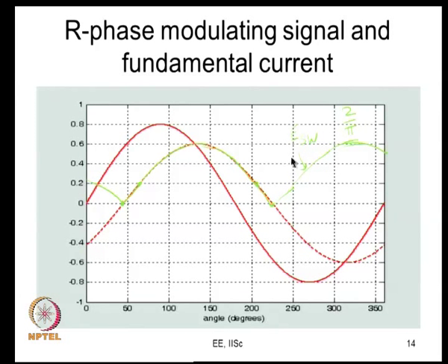On the other hand, if the current amplitude increases, for example, if the current amplitude doubles, the corresponding switching energy loss peak value will also double. Therefore, the average loss will double. But when the current amplitude is the same, given as some 0.6 per unit here, and the power factor changes, then the switching is not going to change. Thus, for sine triangle PWM or any continuous PWM, the switching loss does not vary with power factor, as we already discussed yesterday.